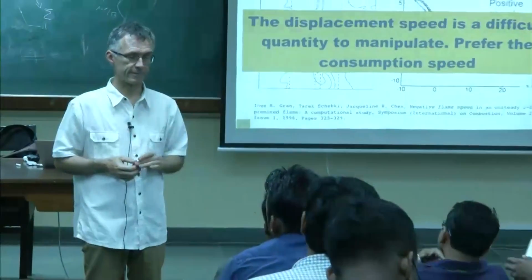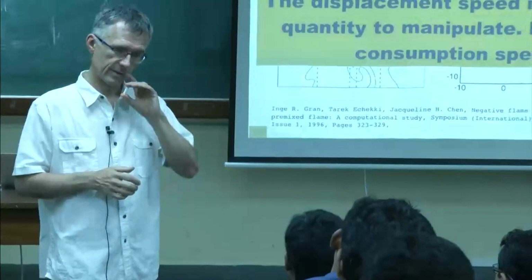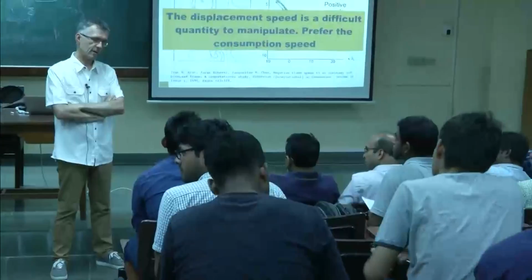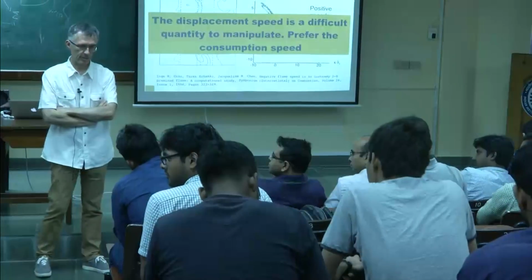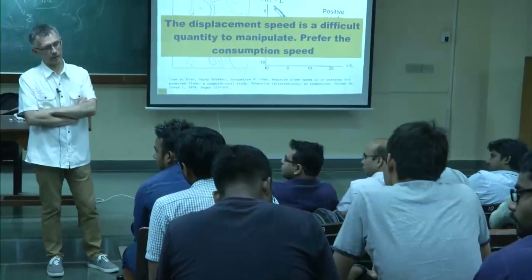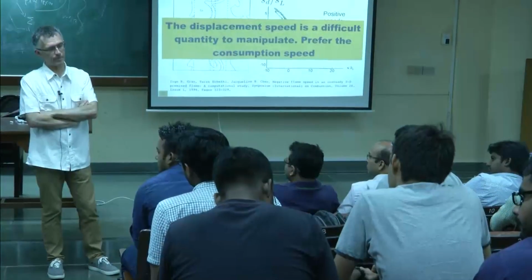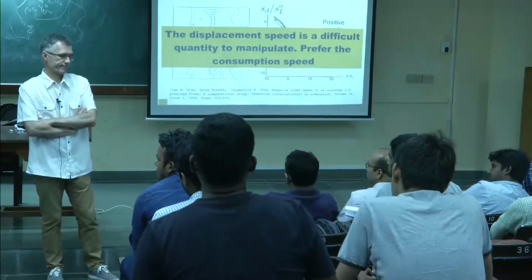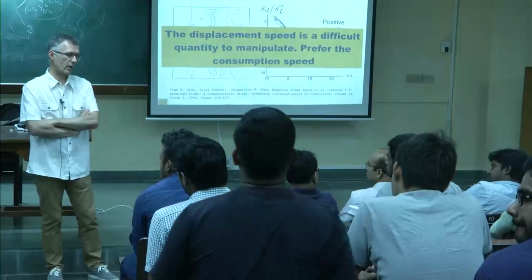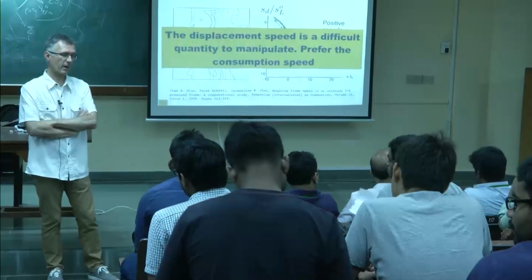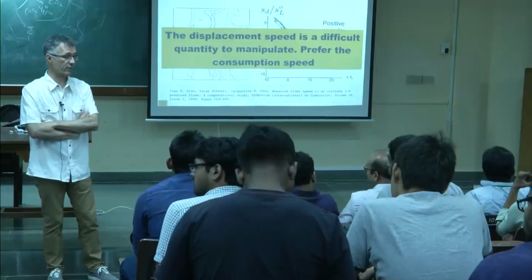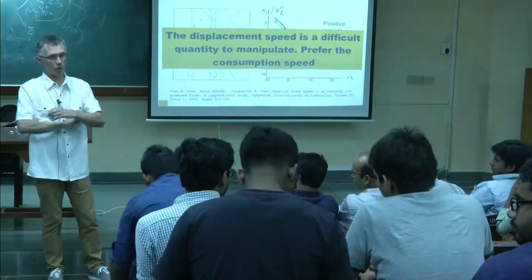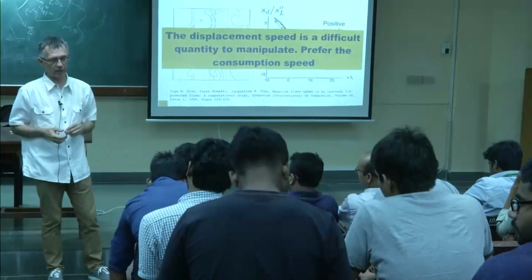They are invariant. And then this definition of flame speed, it actually comes from the study of 1D planar flames, right? Yeah. So how good is it to extend the same terminology to a flame which is highly curved? I think it's because of this reason I get all the negative and very high values. Even for a 1D flame, you can have strange displacement speeds. No, it would be the same. Even for a 1D flame, you can have negative values of displacement speeds too. Of course, when it's curved and stretched, then anything can happen.